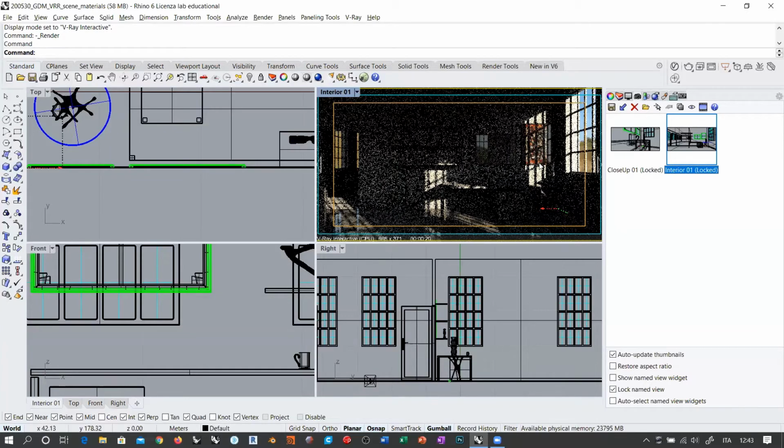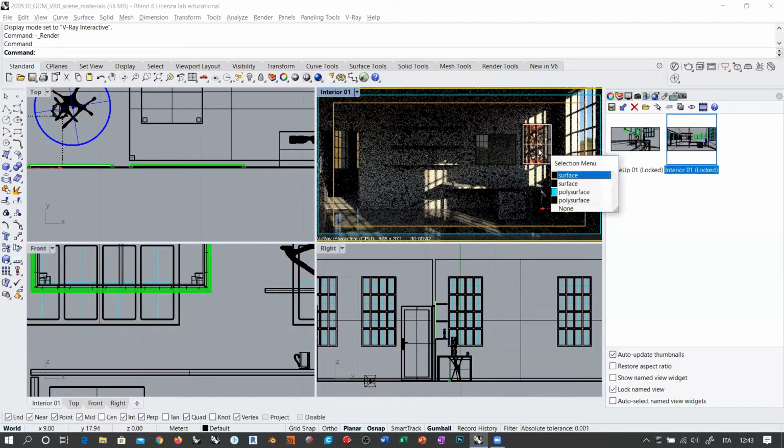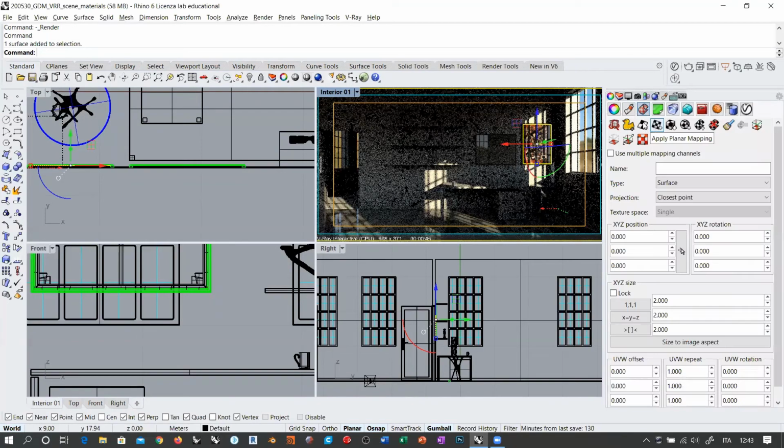You see that in this case, I didn't have to texture map two surfaces, because the standard texture mapping for the diffuse color of a surface is surface mapping. So having these two surfaces here with no texture mapping at all is the same as having the surface with surface mapping.